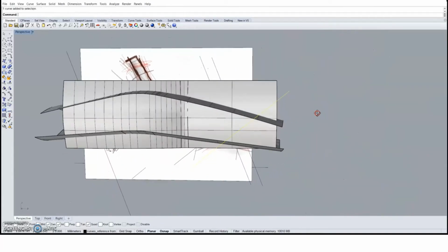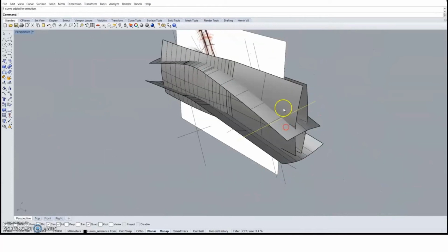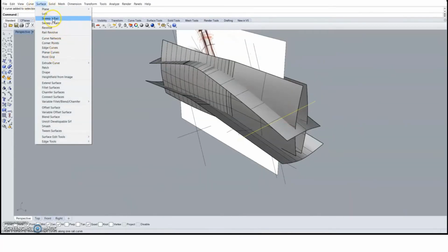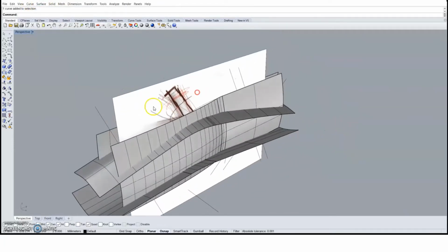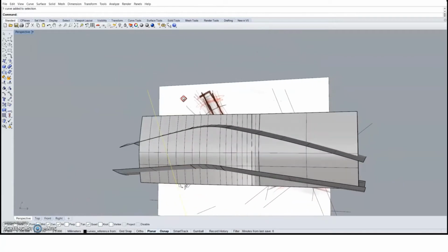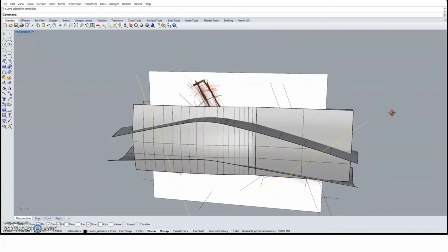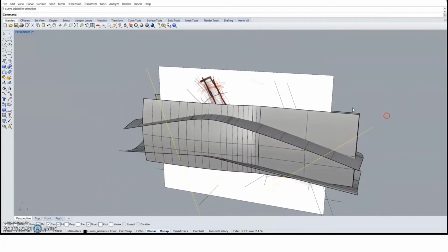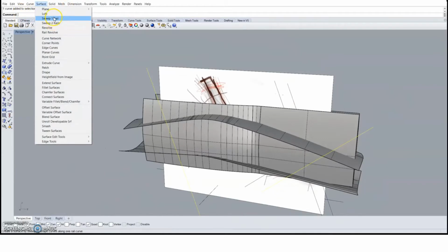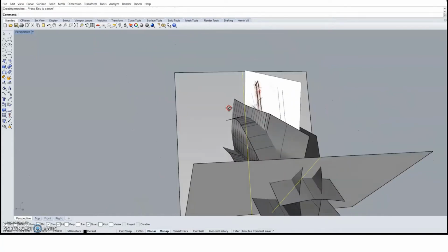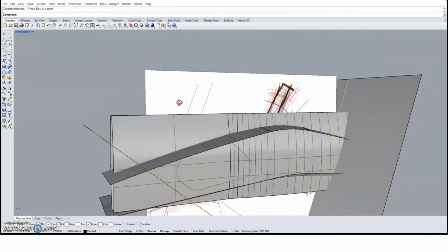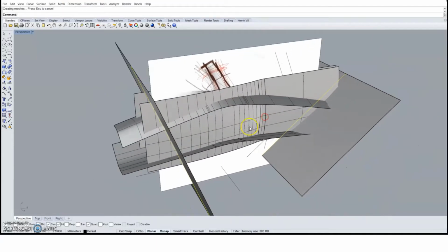And we are continuing to create the other curves and the other surfaces to trim them. This is a much simpler surface. We're going to use surface extrude curve, and basically extrude a straight surface out from the two curves. That will define the two ends of this whole product, the main body.